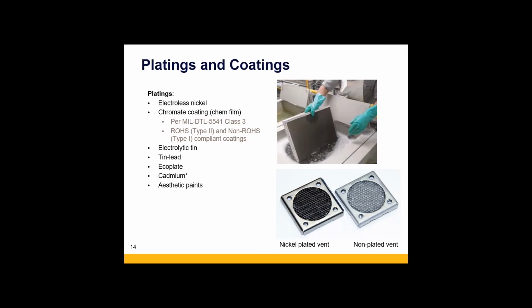But Ben, why does the cadmium happen to have an asterisk next to it? Yeah, the cadmium is actually an old school technology. While it's on a lot of prints from historical designs, and we can do cadmium plating, we prefer and strongly recommend that it isn't designed into new vent designs, just because it's a hazardous material and it can be difficult to work with some of the additional requirements.